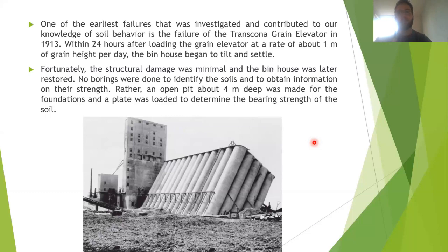The geogrid is the material that you use to make slopes more stable. It's basically a sheet of material, really thin, 2 or 3 millimeters. It's a grid made from plastic or fiber, depending on what you want and what properties you need. On the slopes, you would put a geogrid and put grass bushes there. So you have an eco-friendly slope, but secure enough to hold for the next 50 years.